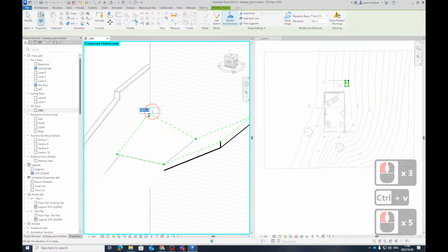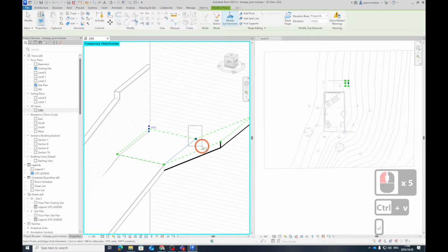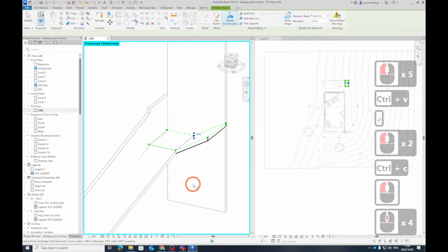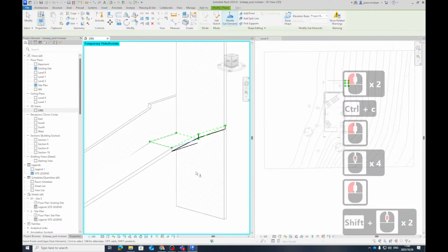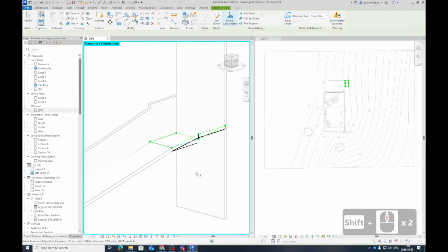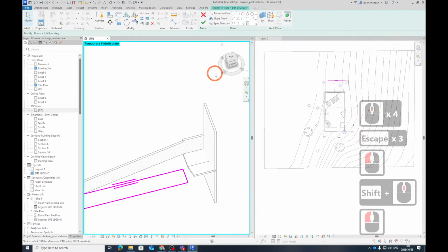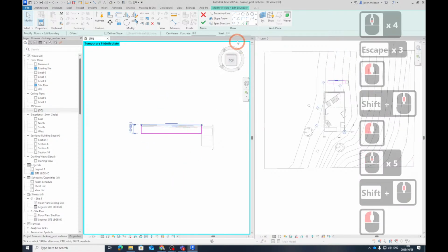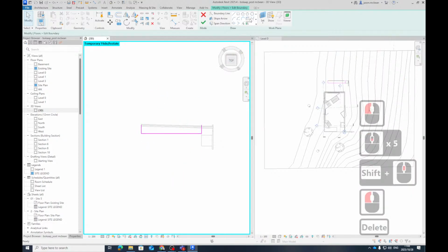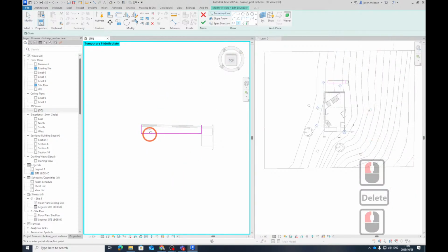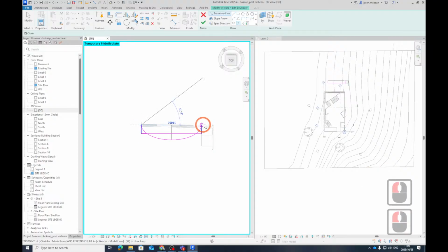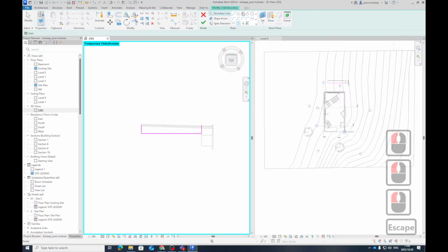But now Revit was trying to do this maths that I'm doing manually now. That's why this thing doesn't like it. So Revit's trying to do this maths. When the maths gets impossible, the thing collapses. Okay. And this works with curves as well. So if I go and edit boundary, and I change this to a curve, so if I add a curve in here, okay, maybe that's not the best curve to add in there because that thing causes havoc.